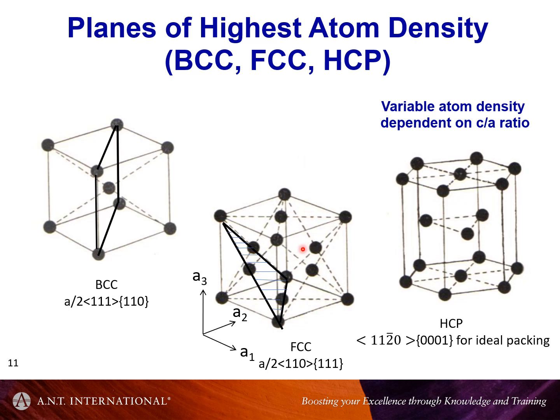So let's get on to what's the difference between HCP, zirconium, and FCC, which is any austenitic alloy, mostly nickel, but most steels are also FCC because of the nickel addition. If you have a sufficiently high level of nickel, above typically 12%, you can have a substantial amount of FCC phase.